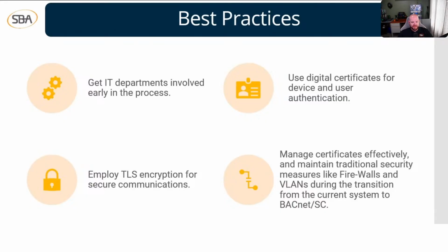Okay. The next thing here is to always employ TLS encryption for secure communications. Remember, this is the big draw with BACnet Secure Connect, right? TLS encryption is encrypting our data packets, our communications between all of our controllers on the network. That encryption is the cybersecurity part. That's what's making things so secure. If you're not employing this, then you're really not using BACnet SC to its full potential. So make sure you're employing TLS encryption.